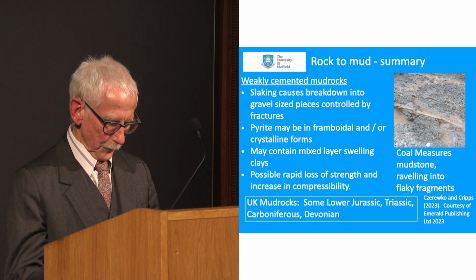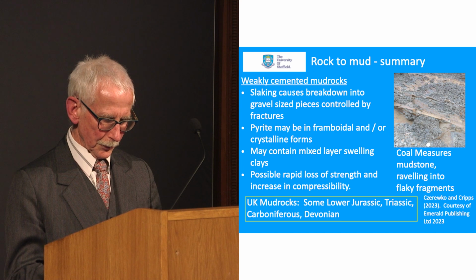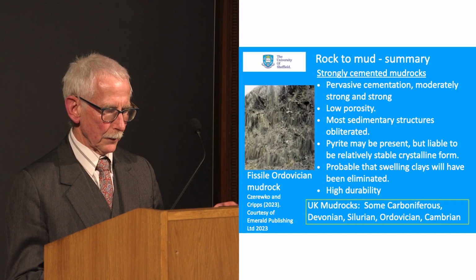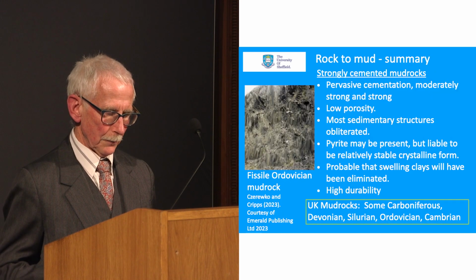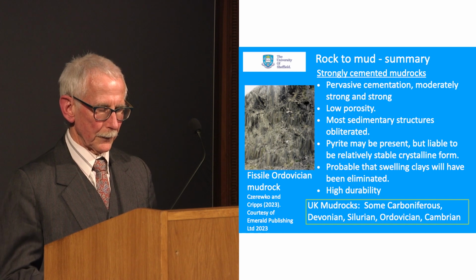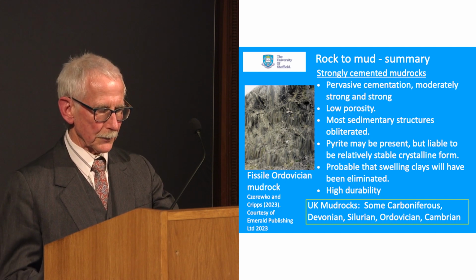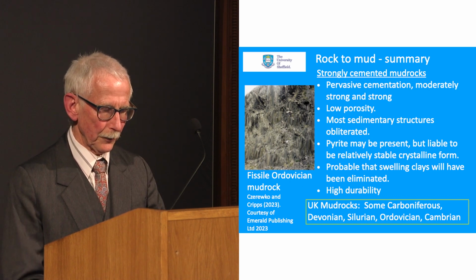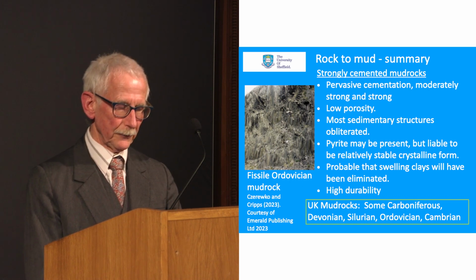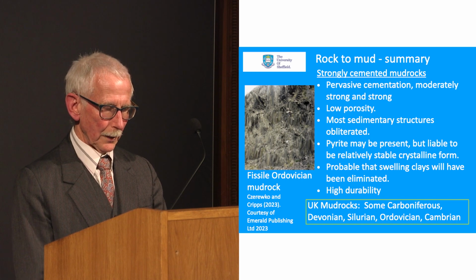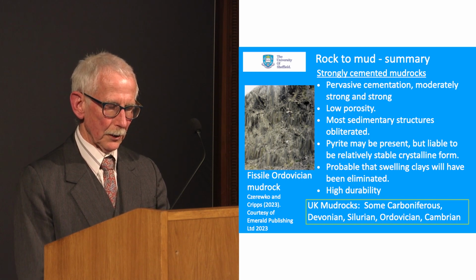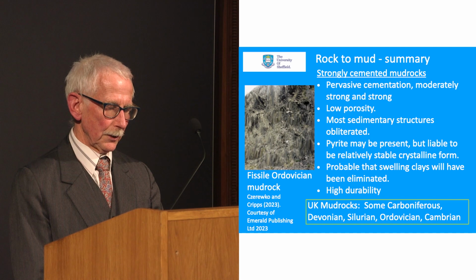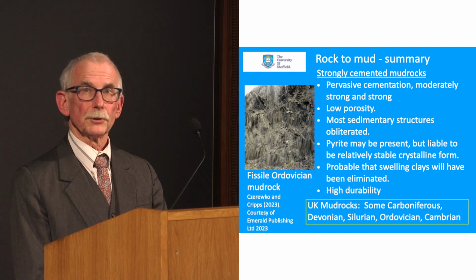And then strongly cemented mud rocks, in which there's a pervasive cement holding the rock together, and there'll be an absence of swelling clays, and pyrite will have been converted into a less reactive crystalline form. Deterioration will be much slower over periods of tens of years and mainly controlled by structures in the rock mass.